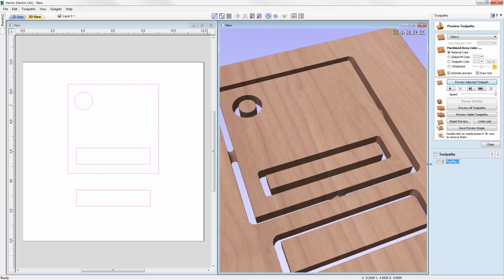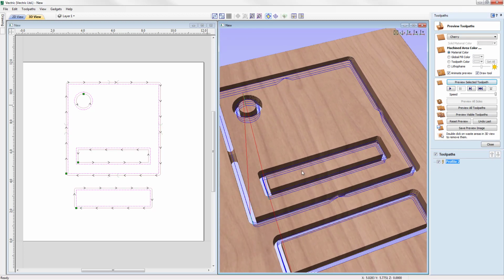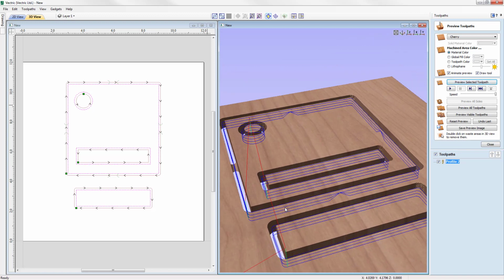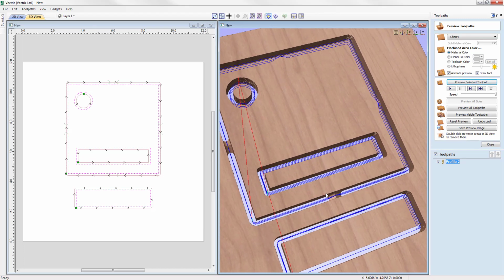And so we can see that with the actual toolpath itself, what's happening is the tool ramps up to the height at the top of the triangle over half of the distance, and then it goes back down again to actually create that triangular tab.